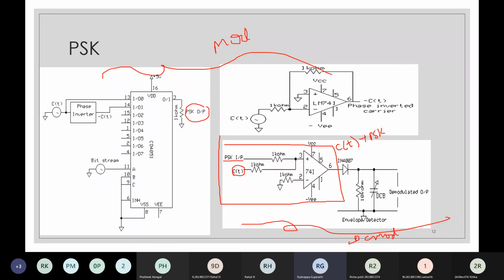So now what happens is, at this point again you can observe that you have a signal which is of this kind. So now again this is an envelope detector. What happens is, during the positive half cycle the diode is on and this charges the capacitor. So when the charge is on, it charges, and when it is off, it tries to discharge through the 10 kilo ohm.